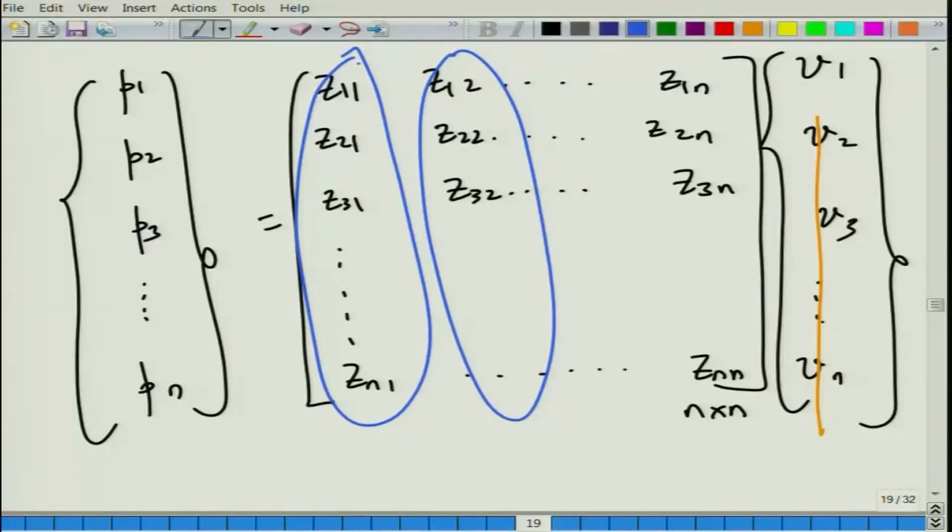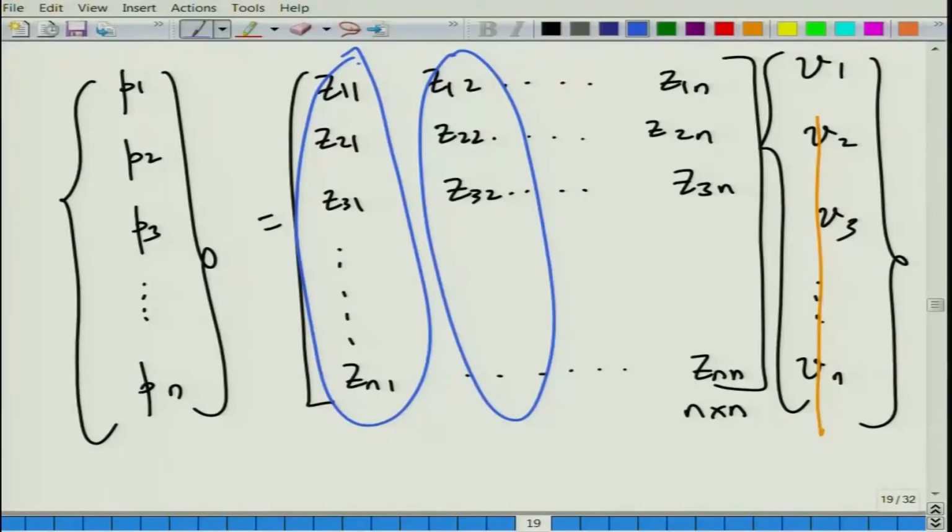We will see soon, but what we will do in this lecture, because we are going to use the impedance matrix formulation to characterize a rectangular chamber and a circular chamber in this course, and I might just talk a little bit about elliptical mufflers using analytical functions, just a glimpse of that, is that an impedance matrix would be very much suited for analysis of such reactive chamber mufflers.